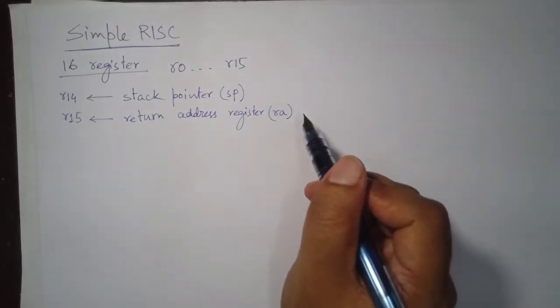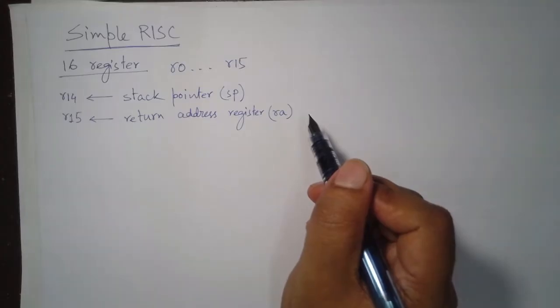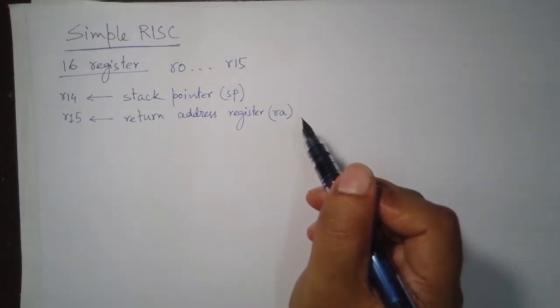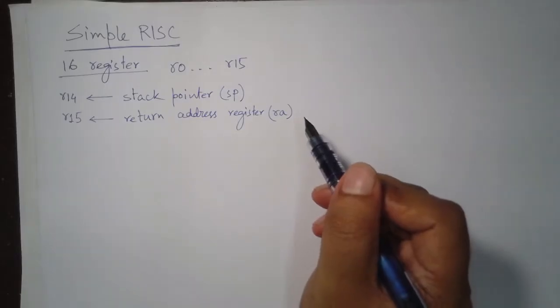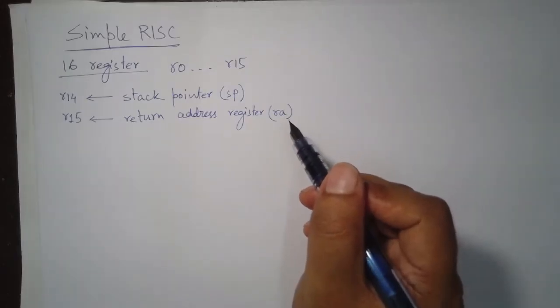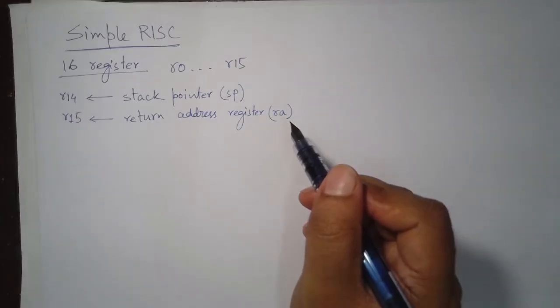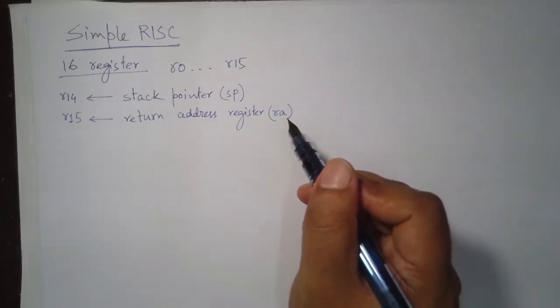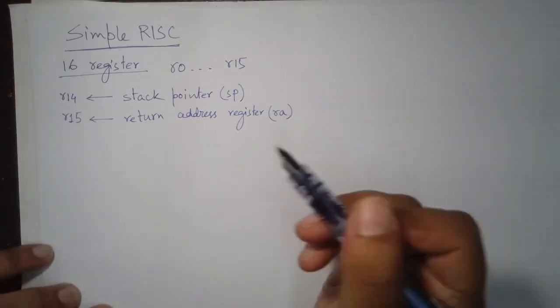The memory will be considered as the von Neumann model. So basically the data and instruction memory are together, one large array of bytes. That's what our memory is. We will have special flags. We will have a special flag register as well, and this flag register will contain the results of the comparison outcome.